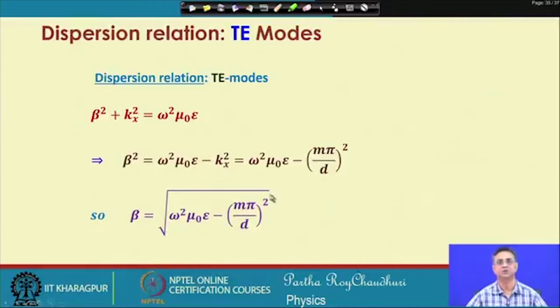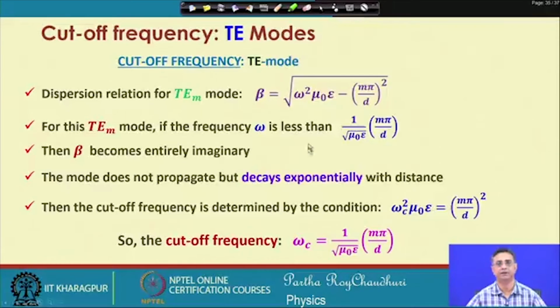So, this is the dispersion relation for the waves, which gives the modes supported by the structure. Knowing the value of m, the waveguide parameter d, the material properties, and omega, we can calculate the propagation constant. This gives the solution for the waves travelling in the medium bound by the two plates, which appears in the wave equation as e to the power of i beta z. Okay. So, the cutoff property: which of the frequencies will be supported.